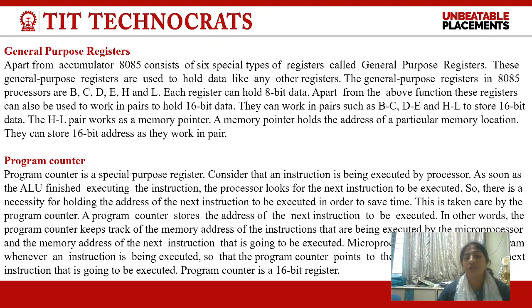Now, next is the program counter. Program counter is a special purpose register. Consider that an instruction is being executed by the processor. As soon as the ALU finishes executing the instruction, the processor looks for the next instruction to be executed. As you fetch the first instruction, you start executing, and the processor will fetch the next upcoming instruction. So there is a necessity for holding the address of the next instruction to be executed in order to save time. This is taken care of by the program counter.